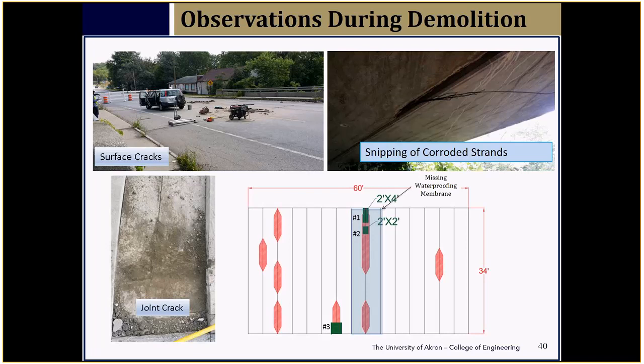Coming back to your comment, we are not saying the paver cannot be used on top of the waterproofing membrane. What we are saying is, I don't have the picture here. I don't want to show that to everyone, but I can show it to you later. We observed that the guys are just driving their rollers, trucks, everything from one side of the bridge to the other side before the paving is done. That's the problem. There are a lot of small aggregates, grit, sharp material, everything sitting on the bridge. They did not blow it off yet, but they are driving their heavy trucks on top of it.